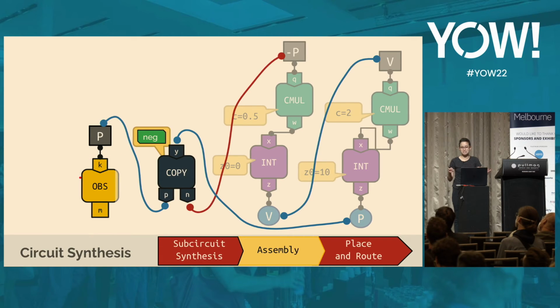And so the assembly procedure basically routes together signals from where they're produced to where they're needed. For example, V is routed from here to here. With one important caveat: because we're using analog currents to do computation, you cannot use an analog current more than once. Because when you split a signal, because of Kirchhoff's law, you change the signal's values. So you have to also insert copiers. And so the assembly process will figure out where to intelligently insert a copier when necessary.